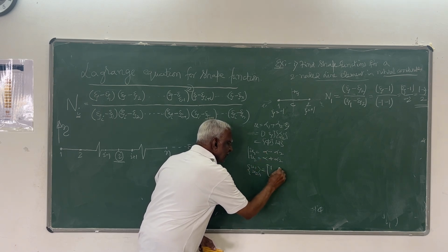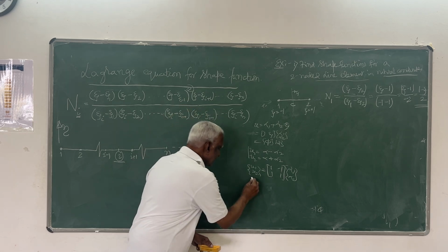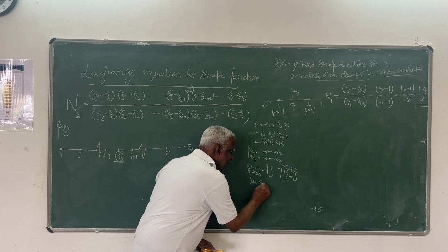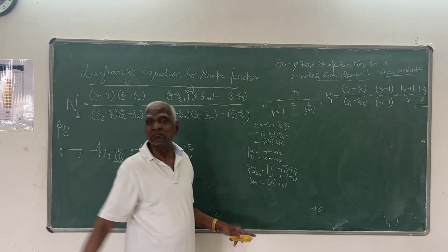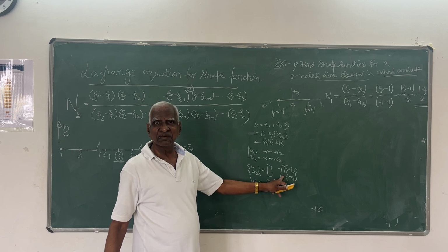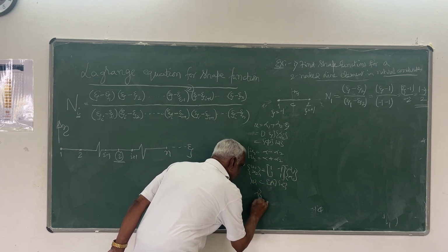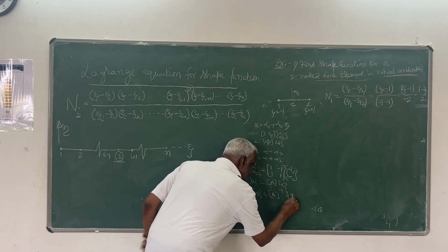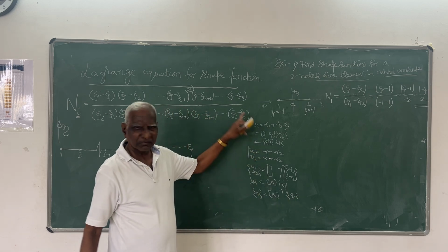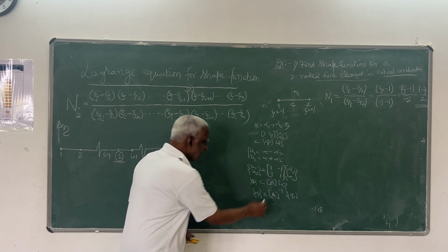Right? This is 1 minus 1, alpha 1, alpha 2. This is your U matrix, this is A matrix, this is A inverse. Therefore alpha is A inverse Q. This is Q, the nodal displacement. I don't call it U. So what is A inverse?